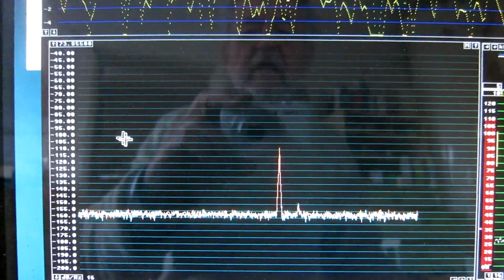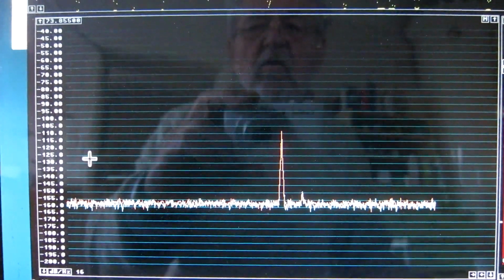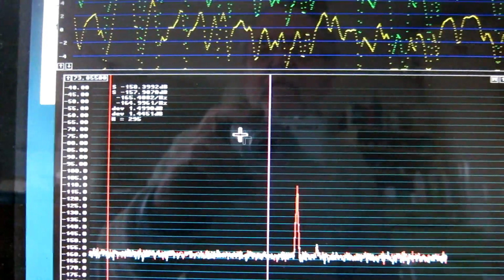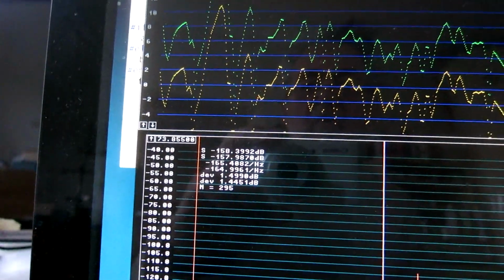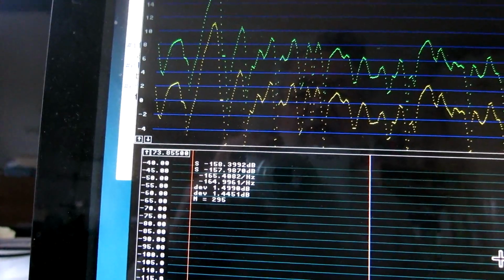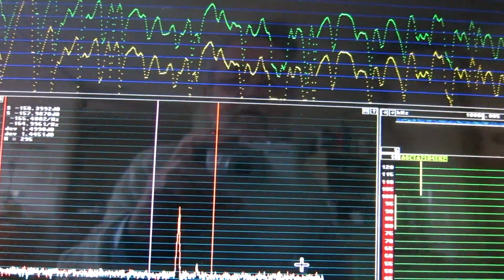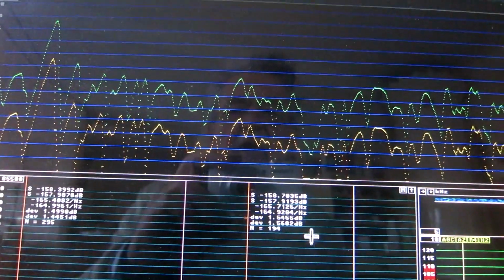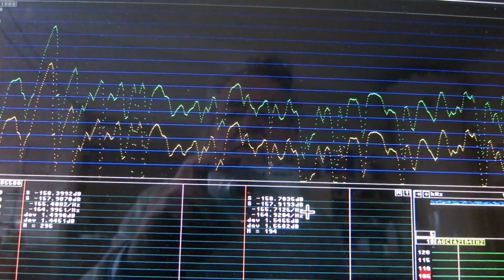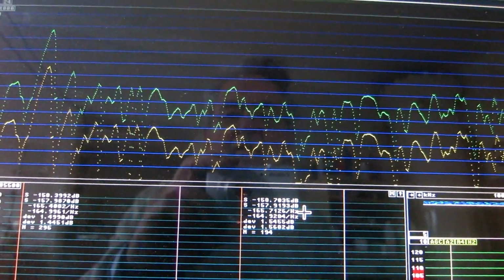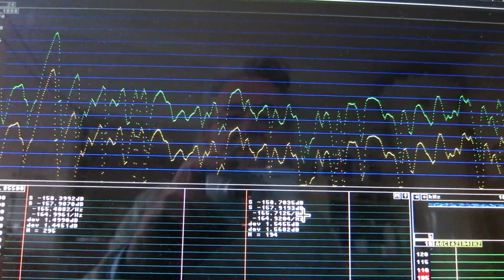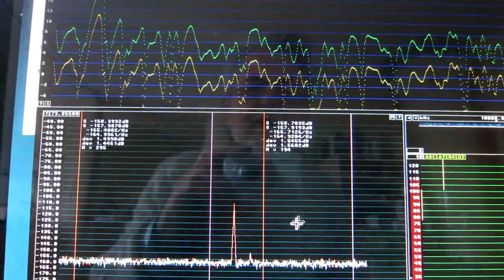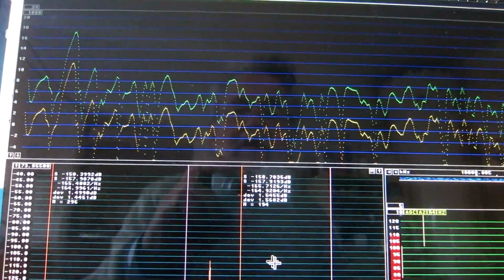It is immediately clear that the uncorrelated noise did not change much. Here is what I had before, 164.9 or 165.4. And here is at 20 dB lower power, and it differs by almost nothing. 0.3 dB in channel 1 and 0.1 dB in channel 2. And it could be random variations.